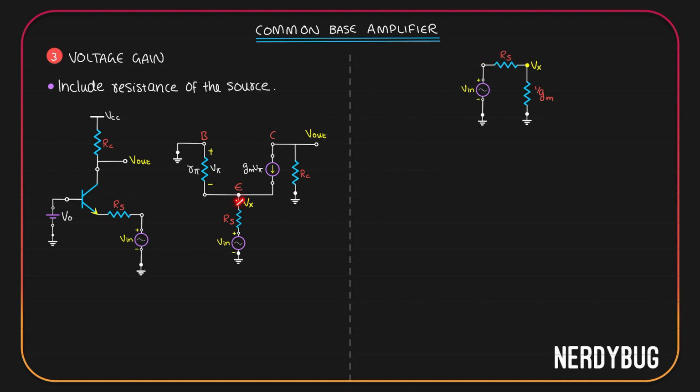Over here, I have marked the point as X and potential is Vx. Over here also, I have Vx. And the rest of the circuit is equivalent to a resistance of 1 by Gm. I modeled it with a resistor of 1 by Gm. Now, from this, I can easily find out what will be the potential that I get at this point.